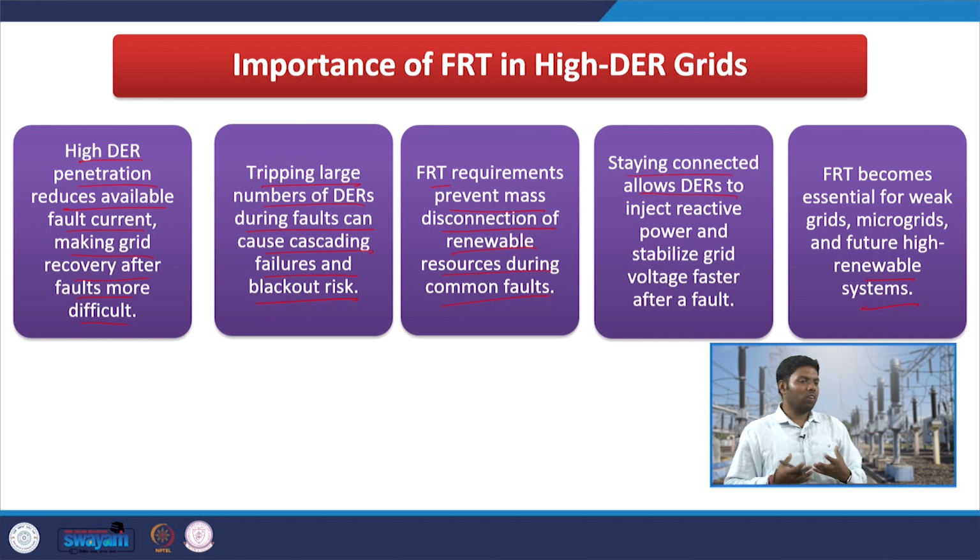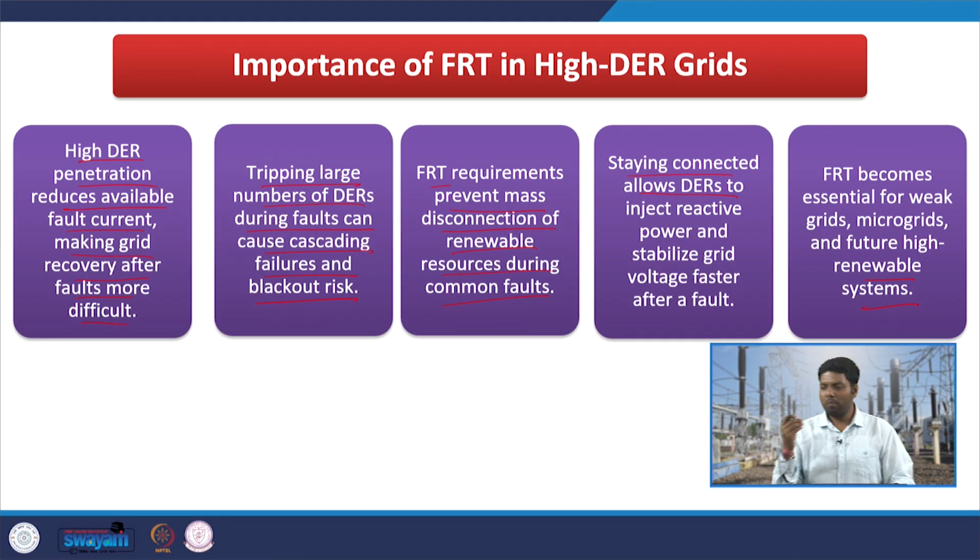Or if you have a microgrid, at the point of common coupling the voltage must be maintained to restore the service or to cope with the faulted condition. At that time, a DER which can locally supply reactive power or boost your voltage will be helpful.